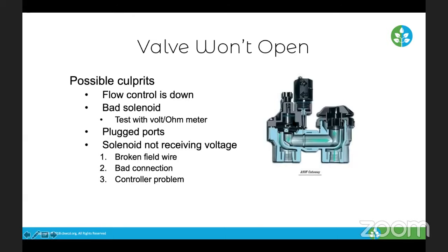That has happened to me quite a few times, especially in commercial maintenance. Let's say the valve turned on, and there's somebody who knows enough to be dangerous and doesn't want the water on, so they open the valve and then turn it down. Let's say they were watching the stars at night on a blanket in the grass area. I don't know what they were doing, but they turn it off, so the valve turns off. A week goes by, two weeks go by, and it looks like the valve is not operating and not opening, but it was just that somebody turned down the flow stem.